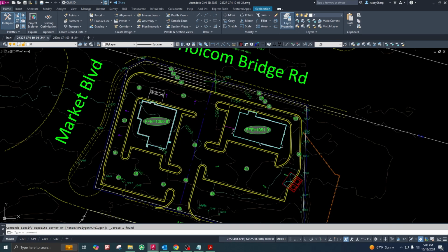Hopefully, when we get into the nitty-gritty, we won't find out that we need a wall, but yeah, we want to define where we want our low points for our inlets, whether they're going to be along the curb, whether they're going to be in the middle of drive aisles. We're going to set FFEs for our buildings, and then just kind of work from there.